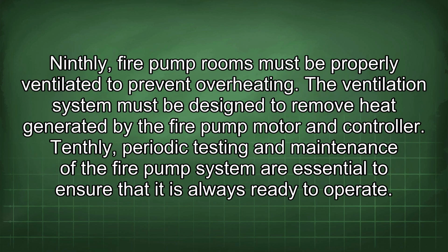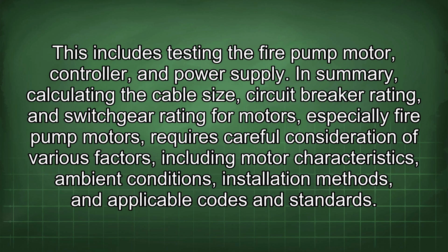Ninthly, fire pump rooms must be properly ventilated to prevent overheating. The ventilation system must be designed to remove heat generated by the fire pump motor and controller. Tenthly, periodic testing and maintenance of the fire pump system are essential to ensure that it is always ready to operate. This includes testing the fire pump motor, controller, and power supply.